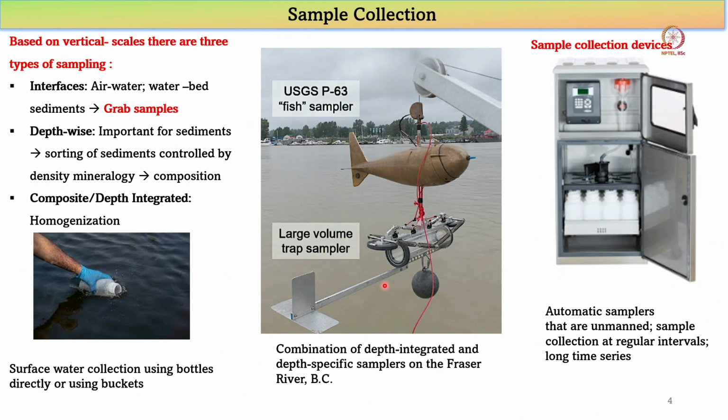Okay, the heavier the mineral is, the more it will settle towards the bottom of the channel. So there is a natural segregation of different types of minerals along the depth axis. So therefore, if you are doing a sedimentological analysis, it is extremely important that you collect samples from different depths.